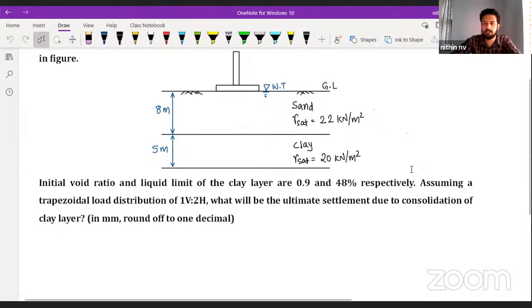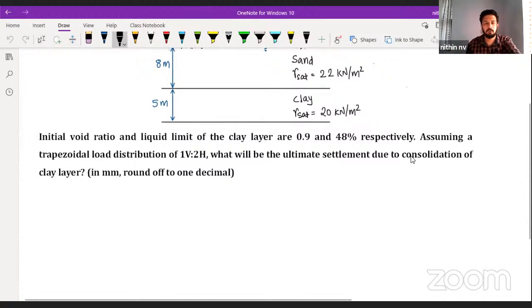Tell me how much you are getting the CC value. So SF, according to this given data, we are using this equation. Any equation you can use depends on the given data. So final effective stress divided by initial effective stress. See, can I write this final effective stress as initial effective stress plus change in effective stress?